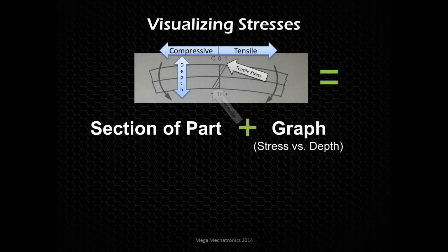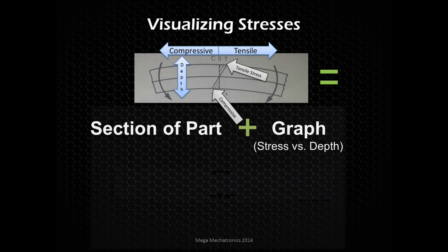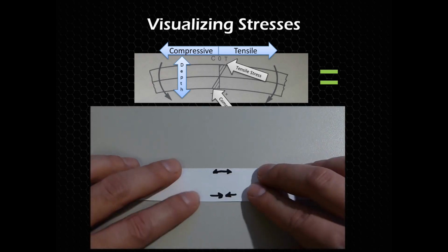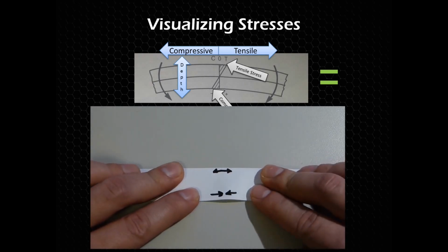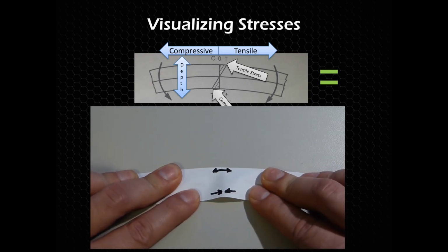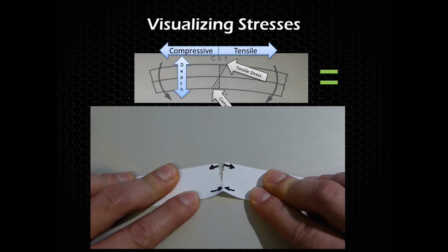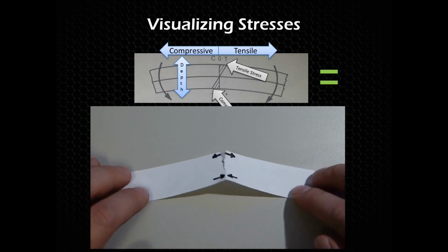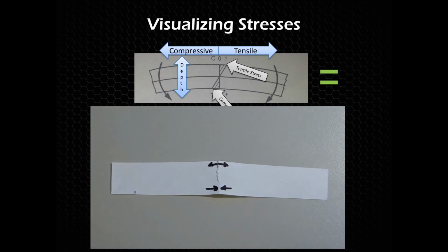And that's typically how parts react to stresses, where the surfaces see the maximum stress. And in our video example, you can again see how I'm bending that piece of paper, and it's going to pull apart at the top because it's under tensile, and then you see it buckling at the bottom because that paper is trying to come together, but it'll buckle up.